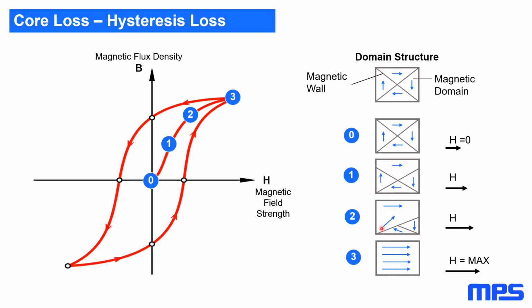The core losses occur when the magnetic moment gets stuck in the crystal structure, and when it finally succeeds in breaking free of the structure and points in the right direction. At this moment the core losses happen, and some heat is dissipated for the hysteresis loss.